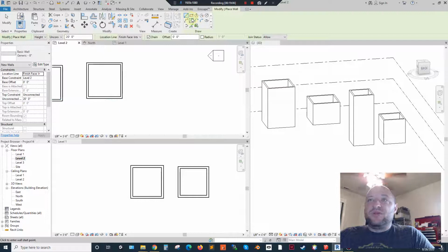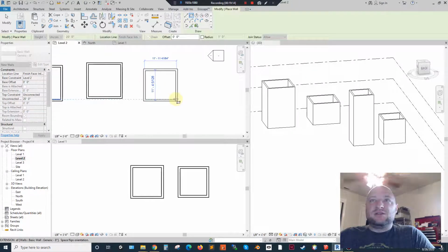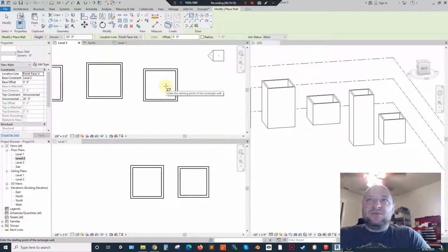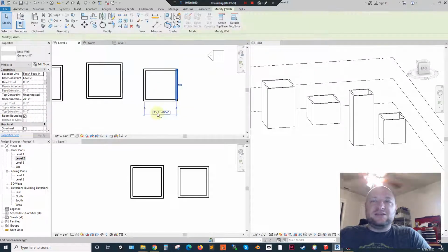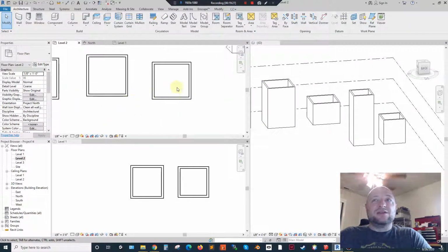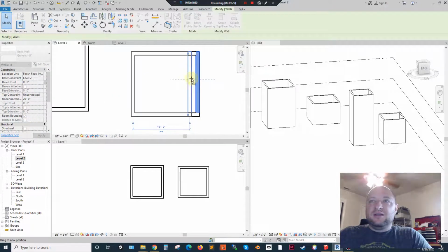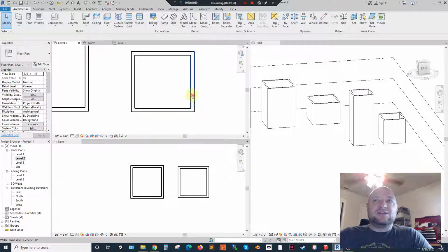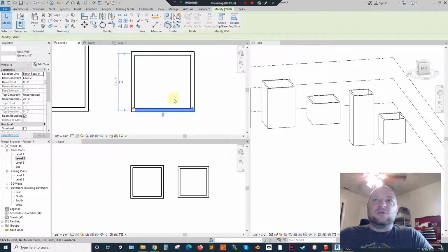Finally, last couple things is just these extra drawing tools up here. So by default, we're starting with the line tool. I can click on rectangle and it's just going to draw a rectangle. I don't usually like drawing like that because the rectangle doesn't necessarily come in with good numbers the way that drawing it manually does, where you get these nice round numbers and then can adjust a little bit from there. Now, if you start dragging this, it will figure itself out and get to a nice snapped, decent number that you can work with.